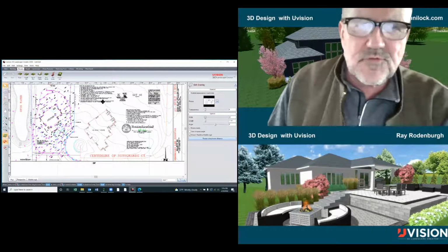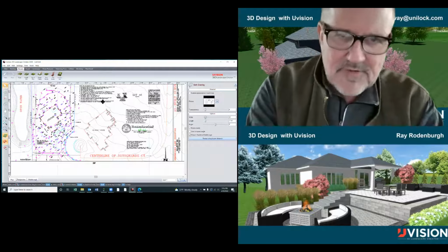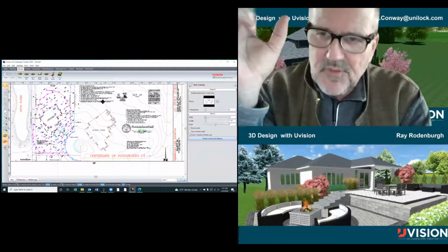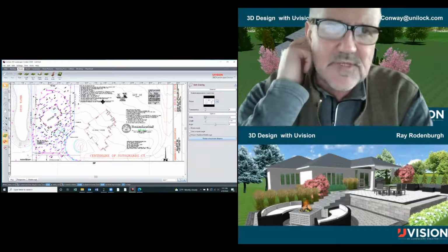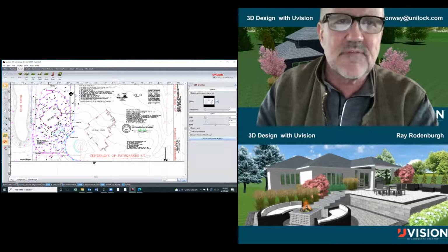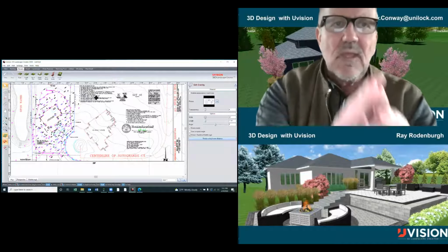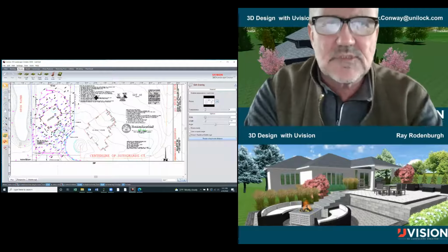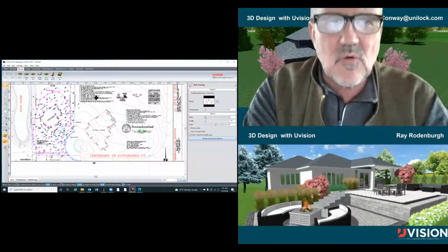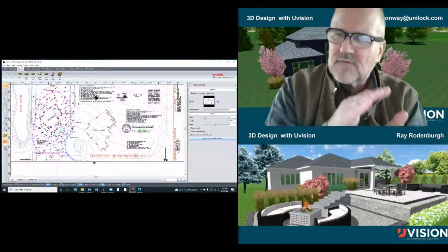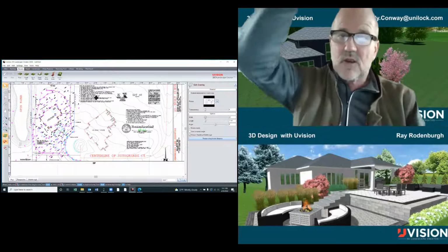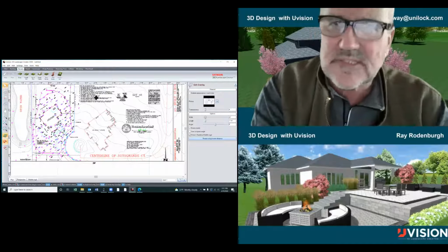Now, when you're contouring, you don't enter 680 feet. With that elevation button that I was putting in, start at 0 and look at this plat. Where it says 677 at the top, right above this arrow, that's what I'm going to start at as my 0. So 678 will be 1, 679 will be 2. I'm only going to go up 3, 4, 5 because I don't want to have Mount Everest on my screen and then start working on the top of it. I just go to basics. It's telling me some stuff.